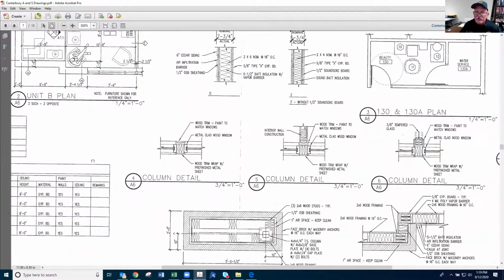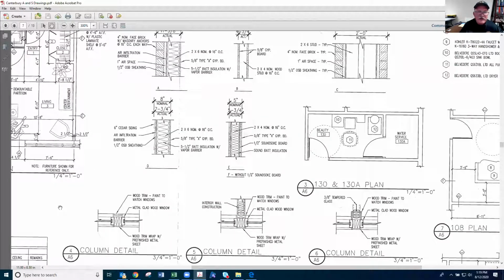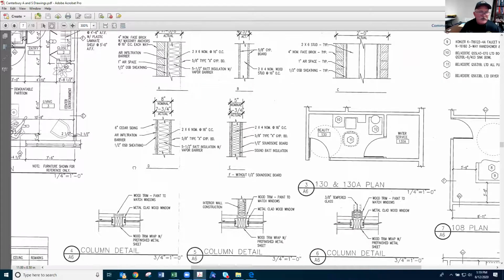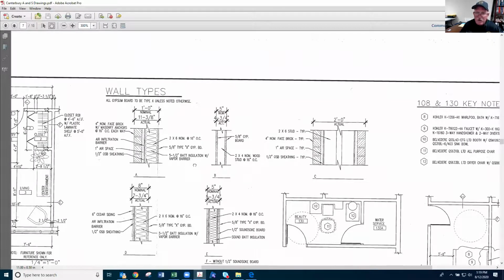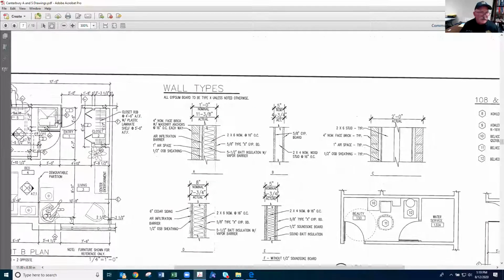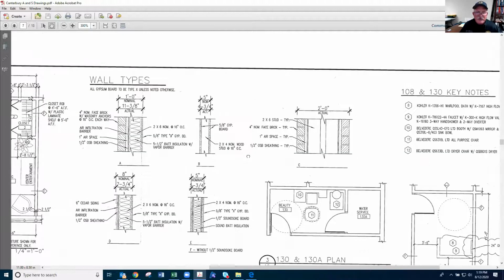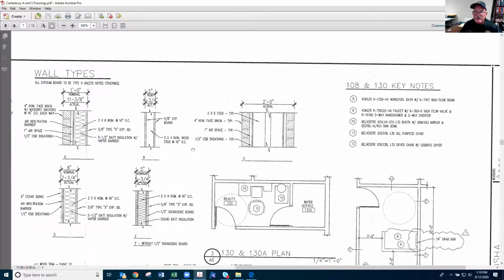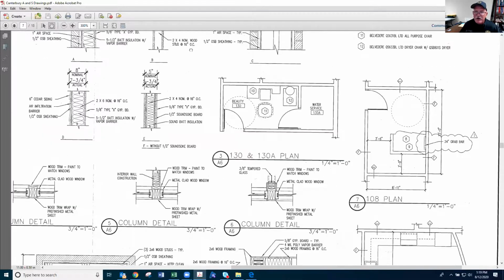Over here, we'll look at Schedule 3. Anyway, you'll find Schedule 1 over here, and it'll tell you the type of wall that goes in there. It'll tell you the type of firewall that goes in here. Okay? It'll tell you how that wall is supposed to be built, how much airspace is supposed to be between them. It tells you the UL rating.